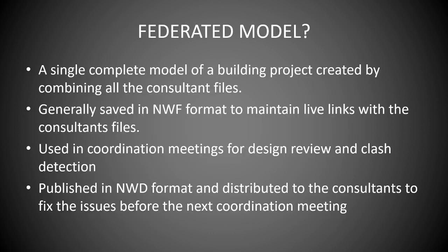Now I will explain what a federated model is. A federated model is a complete model of a building project created by combining all the consultant files. So here I have two models, one is the architecture model and the other is the structure model. Now there could be more than two consultant files, such as an electrical model, a plumbing and mechanical model. But here I have just two models of my facility, that is the structure and architecture models.